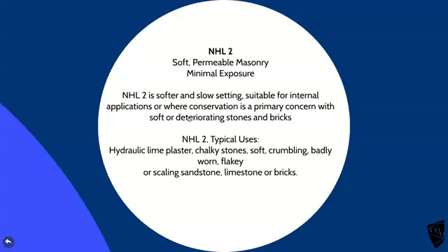Then, as I mentioned previously when we talked about bricks, you use the pointing as the sacrificial part of the construction. It's easier if the pointing, the mortar joints, erode instead of the bricks or the stones, because it's easier and more straightforward to repair. Typical uses for this weak one: use it in a plaster, use it on very soft chalky stones, some limestones you can use it on, and yes, they have used limestone to construct older buildings, not knowing it wasn't going to last terribly long. Useful for repairs on them.